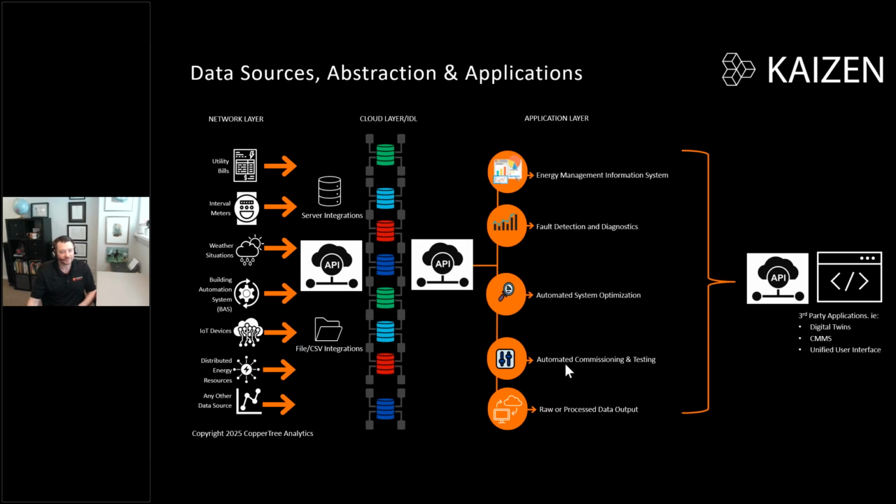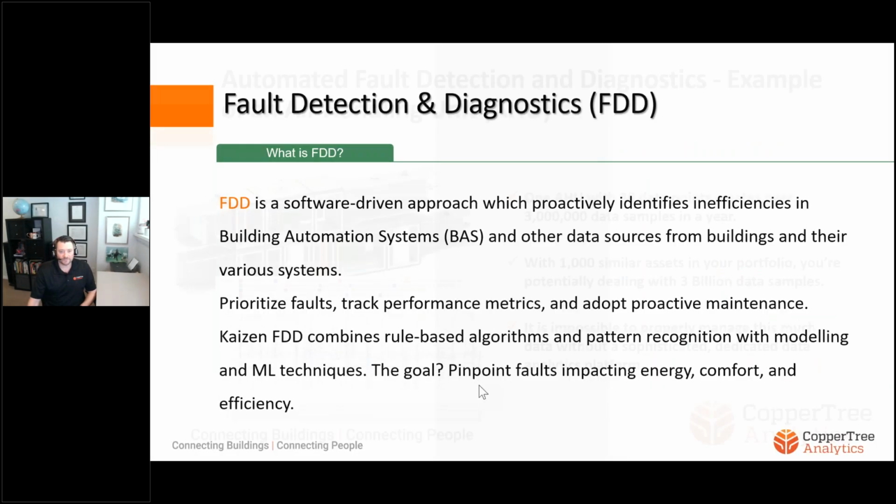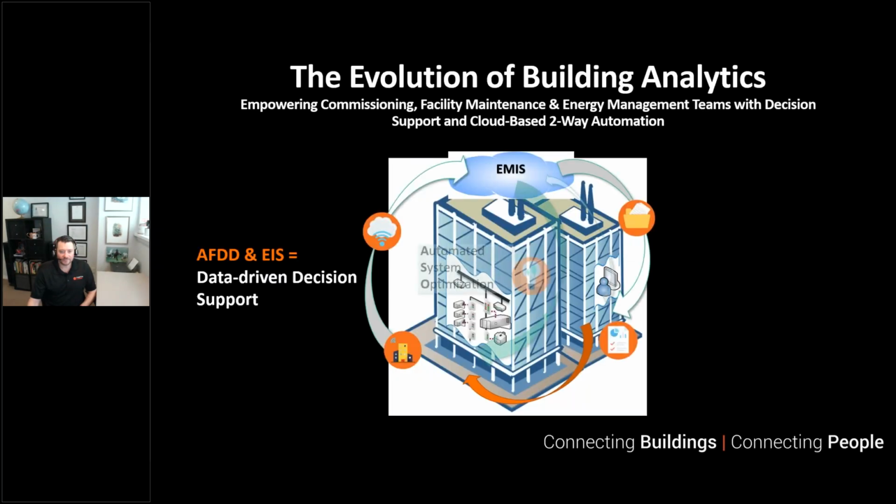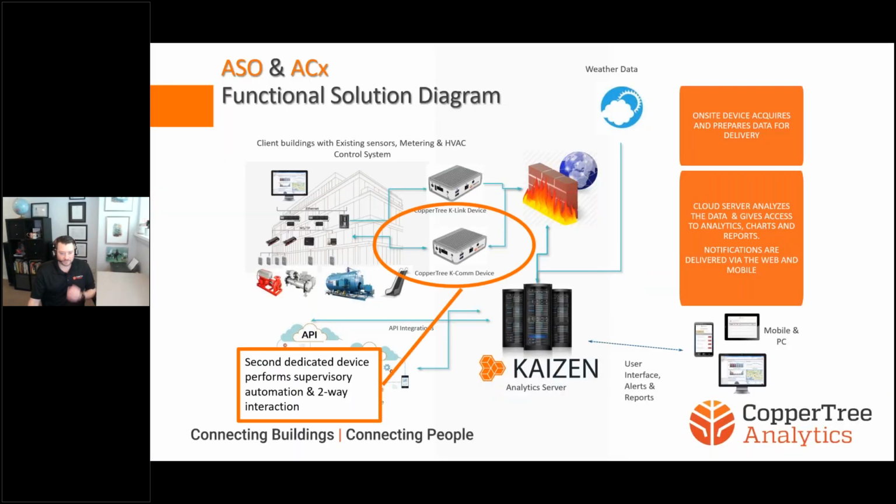Keith, one for me. It's Mike here from AIS. Hey, Mike, how you doing? Very well, great presentation. Thank you. Just an off-the-wall one with the ACX approach for maintenance, in particular fan coil unit controllers and VAV controllers, on an existing installation where the device is installed behind a particularly well-sealed firewall. I get that it has to be written to or have a direct link to the Copper Cube servers, right? But is there a way we can put some packages into an existing edge device and run them locally?